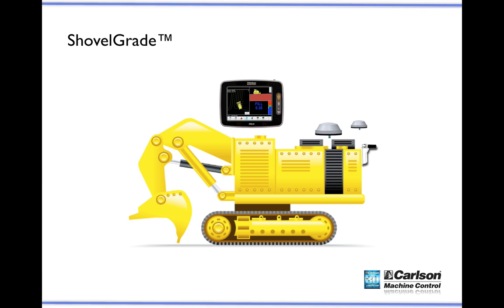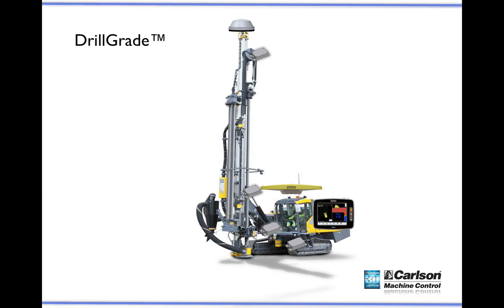Here we see two individual RTK receivers with a wide baseline, because this is a large machine, and the 50 centimeter baseline of the MC Pro VX5 may not be accurate enough. We see the RTK radio, and then we see the body, the boom, the stick, and the bucket axial sensors being applied. All of this being measured, and all the articulation being monitored, fed into Carlson machine control software, and in this case is shovel grade, and then we can monitor the update of the bucket.